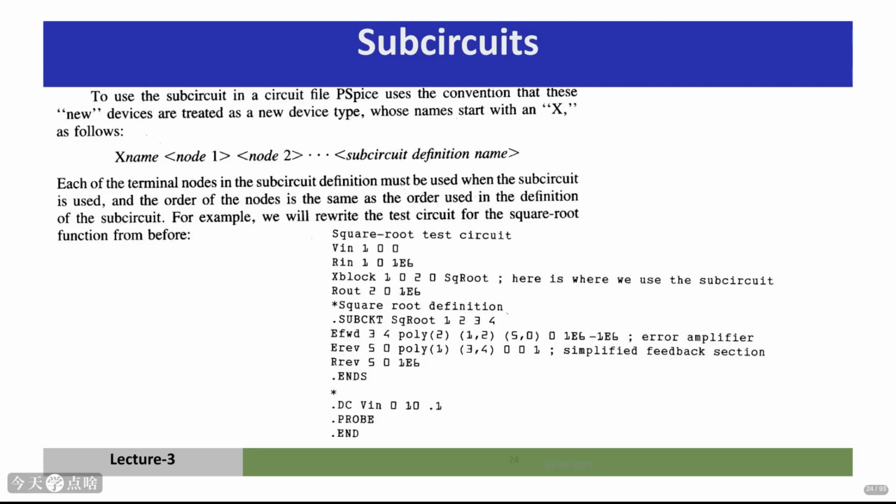So how do you actually use this subcircuit? You use a special component type that starts with an X. The syntax is Xname node1 node2 subcircuit definition name. You must use the exact same order of terminal nodes as you defined in the .SUBCKT block.